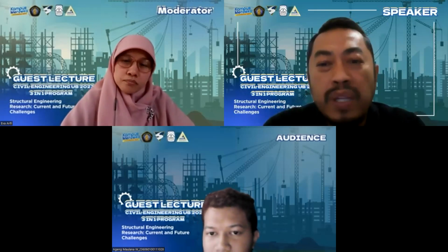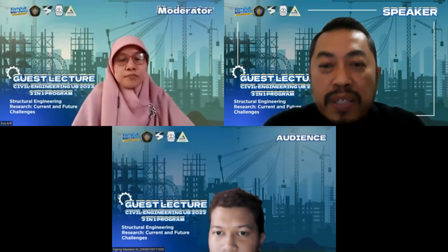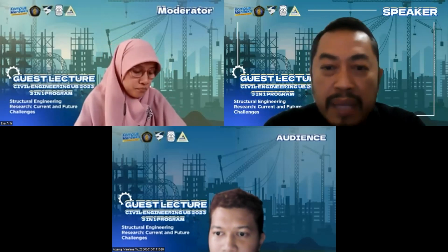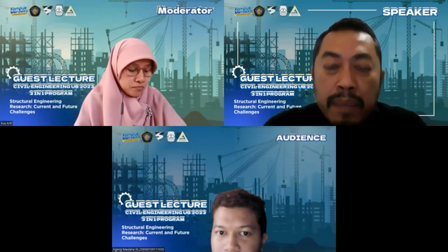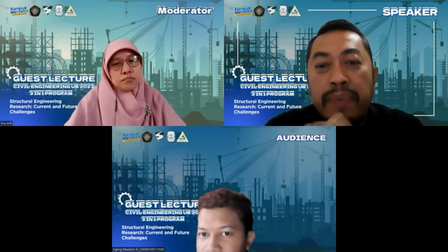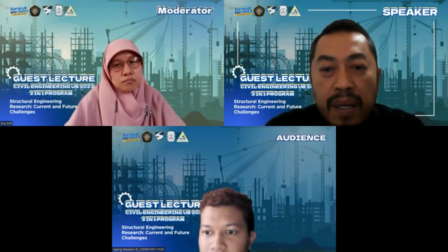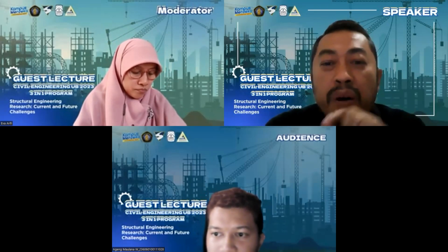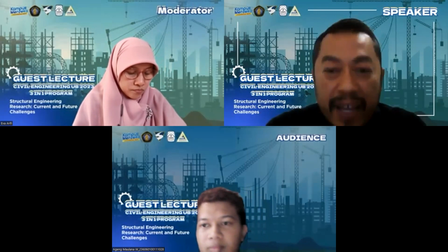Of course, you don't need really high strength for normal structure. You need normal strength concrete, probably 24, 28 is okay. And also bond is not really good. If you do some reinforced concrete structure, you need to have a perfect bond between concrete and steel, for example. And for the bond, I also propose one equation for the bond reduction factor.